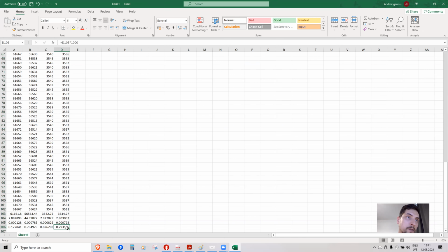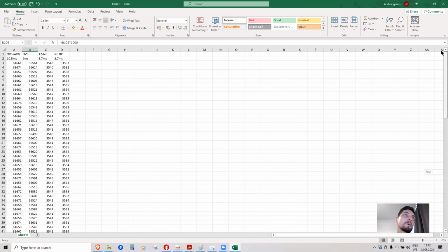and its relative deviation is very similar to having this RC filter on. So that RC filter is pretty small, and maybe the signal is very silent, so there's not much difference here. And when we turned on oversampling with filter, oversampling didn't really change much at the noise level, probably because it's been sampled very quickly and these values don't really differ that much.